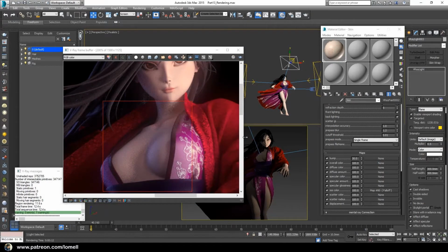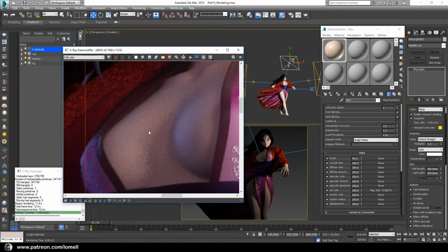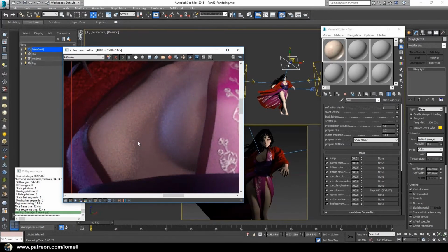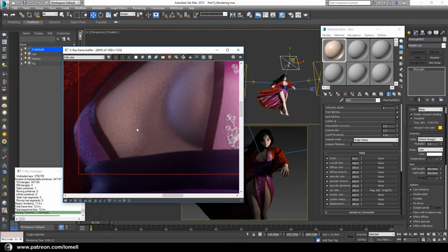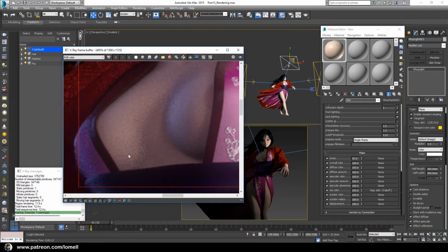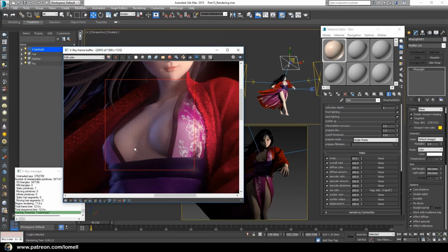Okay, so the next thing we need to do is to eliminate that graininess, that grains on the surface of our objects. And to do that, that graininess pertains to the subdivision level of our material shader, as well as subdivision level for the light. So we have to give it a higher subdivision level to soften this up and to eliminate that grainy surface on our object.